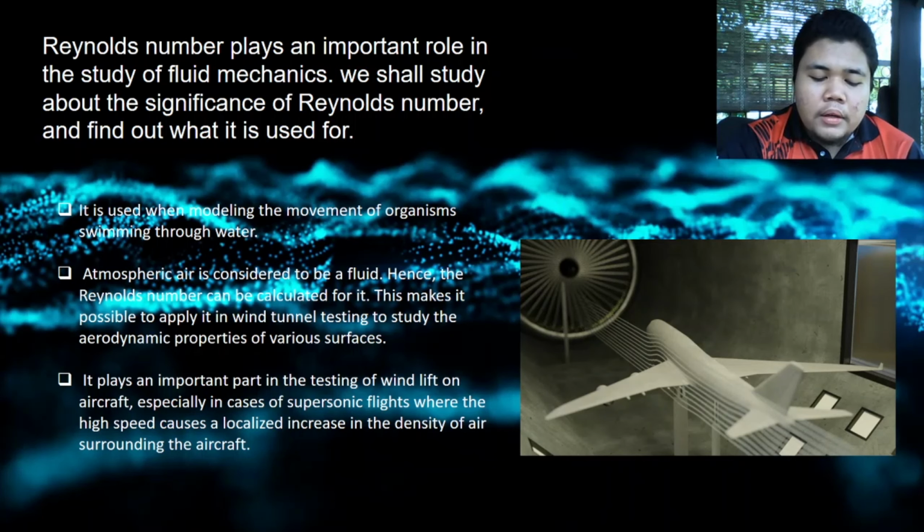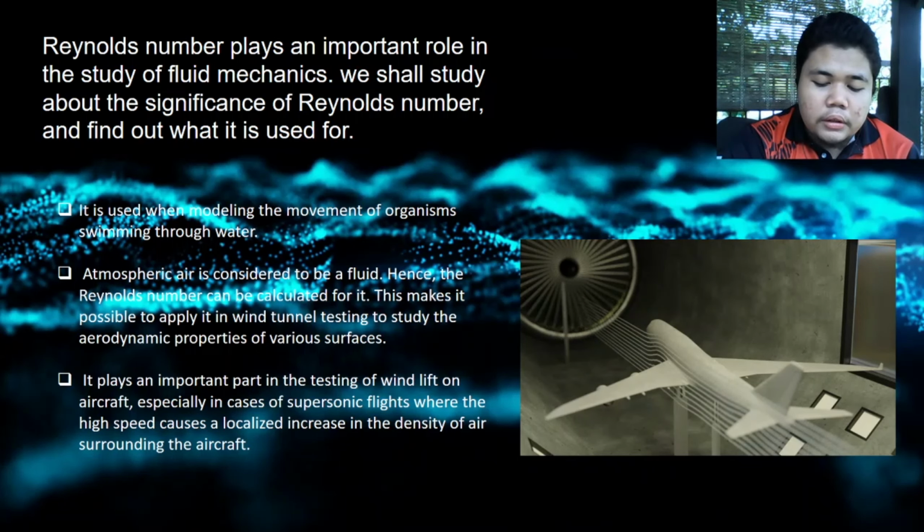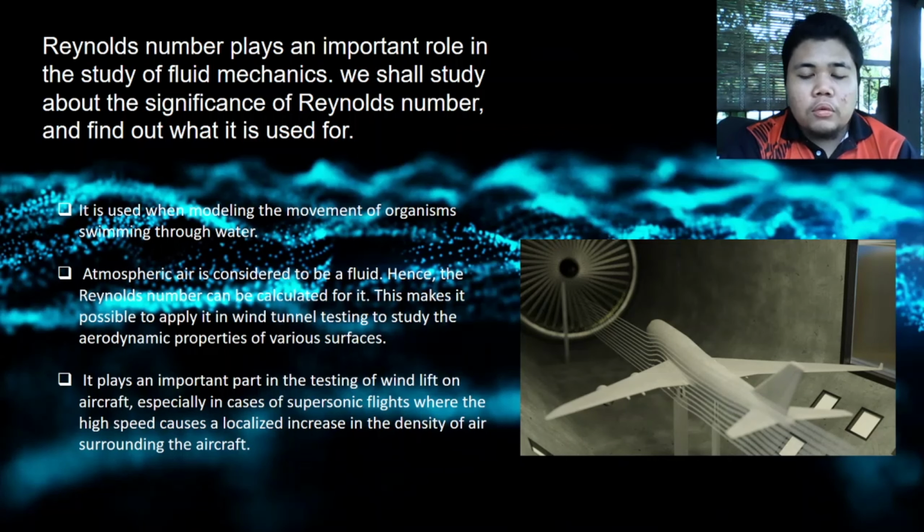Okay, the Reynolds number is large. The viscosity effect is small. If the Reynolds number is large, so the viscosity effect is small. Okay, for practical values, the inertia or density forces dominate and the parasite drag increases with the square of the velocity. However, although the viscosity is unimportant, it may still affect the very thin boundary layer, leading to the creation of turbulent flow.